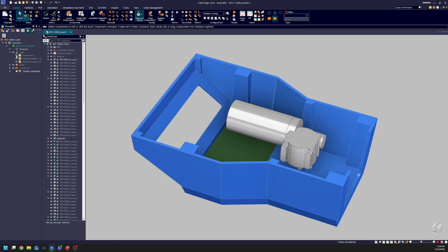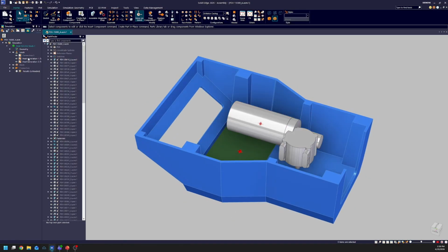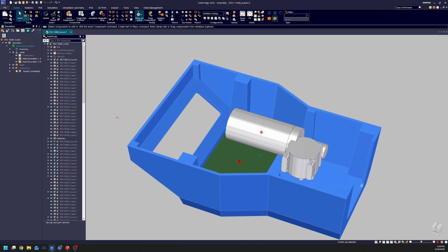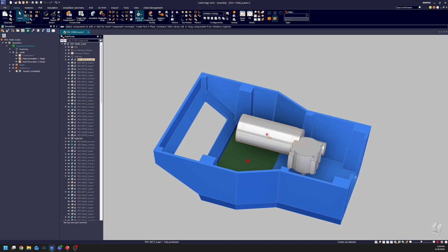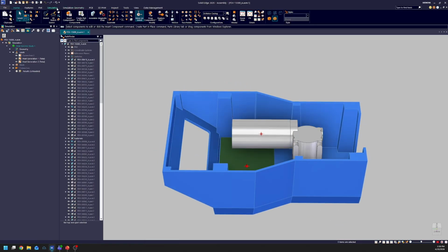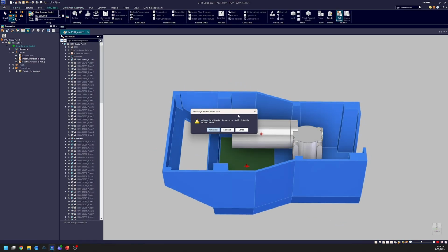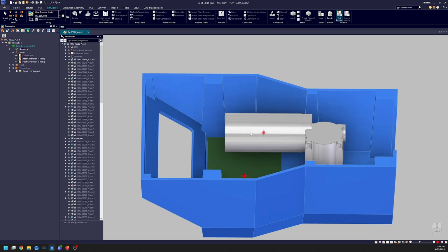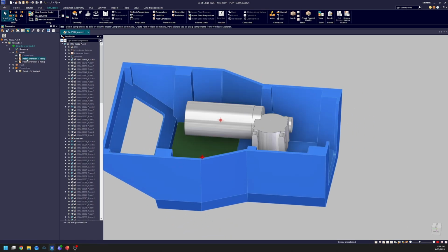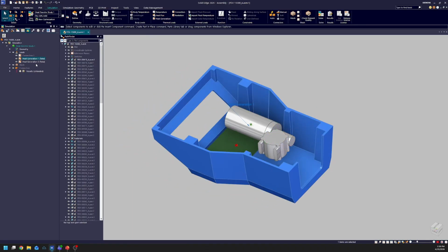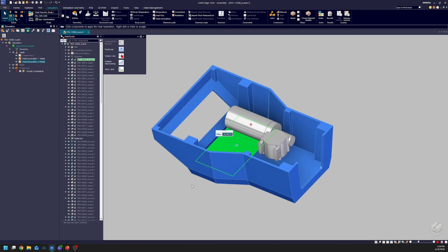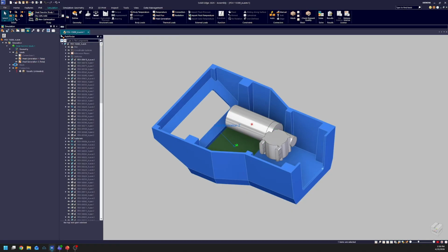And then we have our heat generation loads. So anything that is generating heat here. I believe we have a load of 25 watts on the motor and 10 watts for our PCB. And then our connectors are thermal connectors.